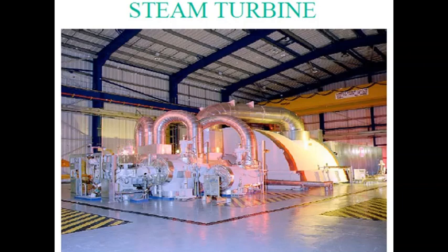These turbines, as the name suggests, handle steam at different pressures, and the HP turbine has the highest pressure steam. From the HP turbine, for bigger units, the exhaust of the HP turbine is used for resuperheating or reheating. After reheating, steam is introduced to the intermediate pressure turbine.